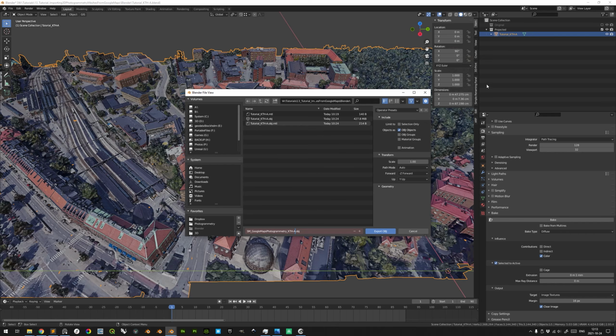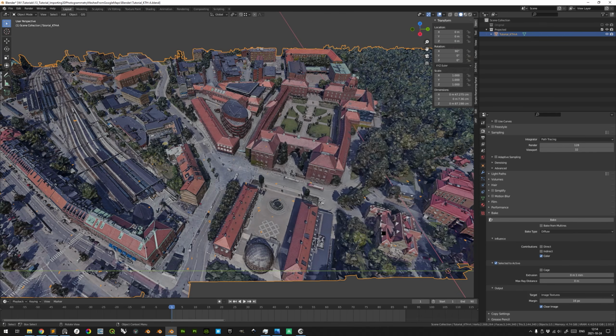Very good. And of course, this is not scaled in any way, but here in Blender we don't have any reference as of now. If we import it into Rhino, perhaps we have, and then you can scale it as you want. Let's make sure that we limit to selection only, and only OBJ objects, and no transformation. And then the geometry, we will not write normals. We will of course include the UV coordinates. We will not write any material. And the modifiers, we do not have any, so that can be left checked or unchecked. All right, let's see, because I think that this will be a slightly smaller file size since we don't include the normal directions, since it is flat shaded anyway.